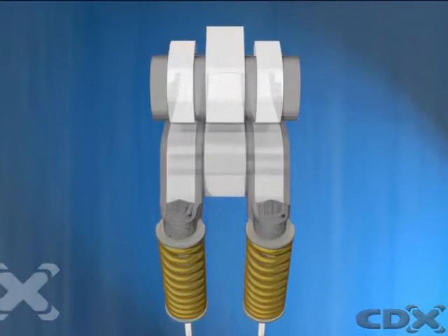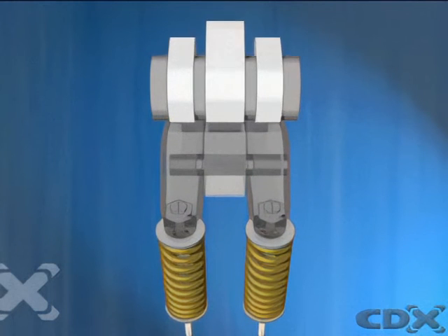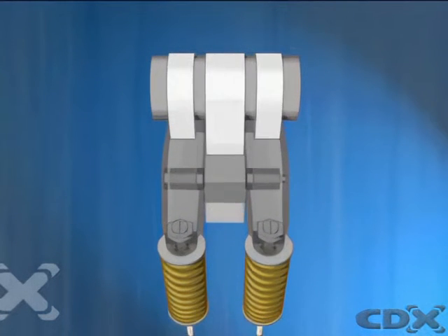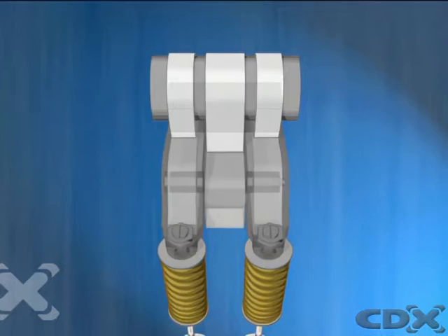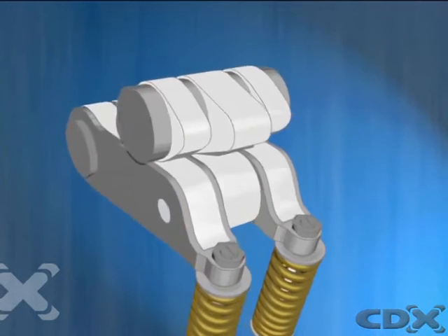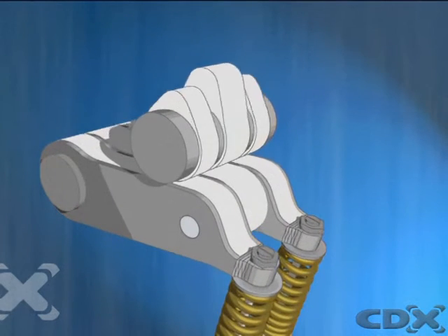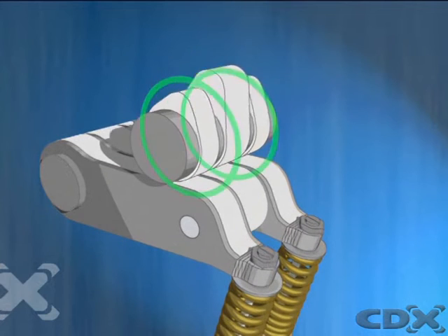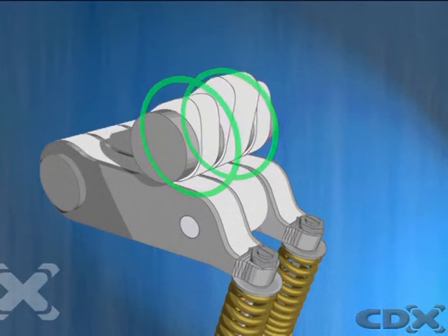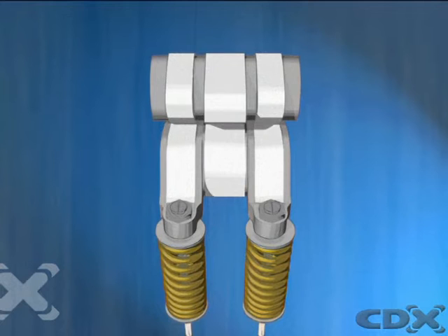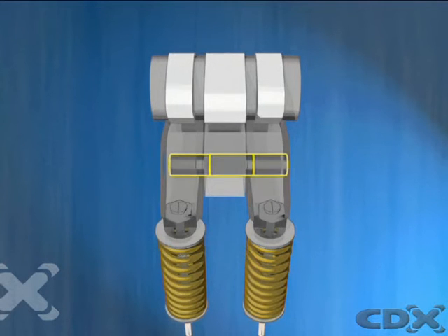When engine speeds fall below the threshold speed, oil pressure is removed from the pin and a spring deactivates the pin. The rocker arms are no longer locked together, and the valves are controlled by the less aggressive outer lobes. Cam-changing VVT can also be used in a similar way to deactivate a second intake valve at low engine speeds, increasing the velocity and swirl of the air-fuel mixture as it enters the combustion chamber.